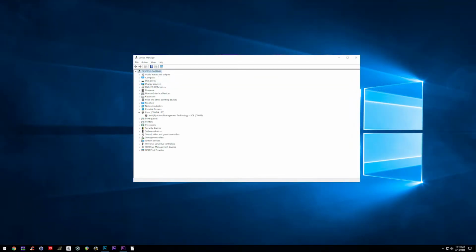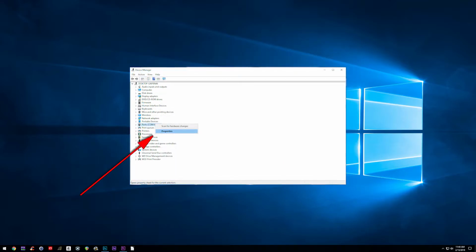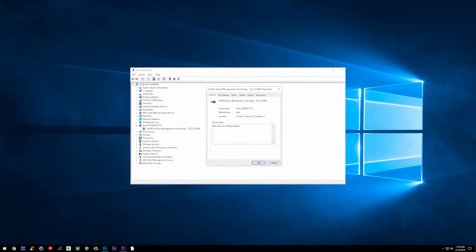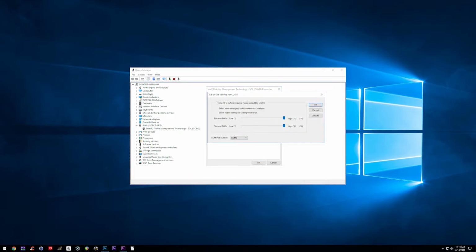If this is not the case, open the Device Manager on your computer, expand the Ports, COM, and LPT tab, right-click on the Casablanca 4A, and choose Properties. Click on the Port Settings tab, then Advanced. Under COM port number, verify that the port selected is between COM 1 and COM 4. Change the port number as necessary, making sure the port selected does not conflict with another device.